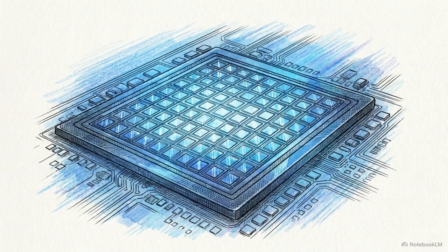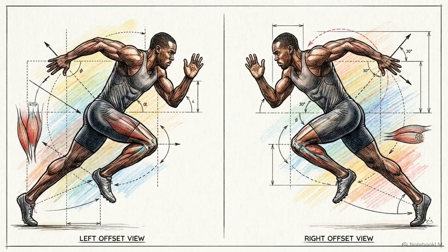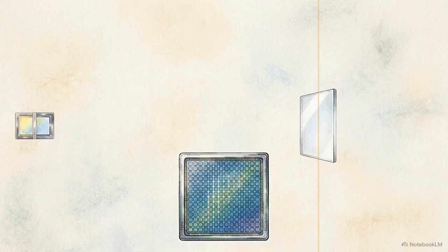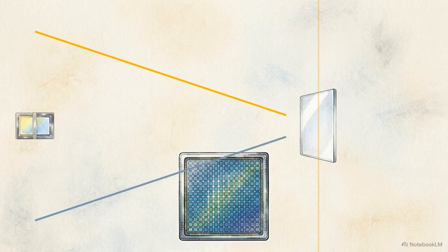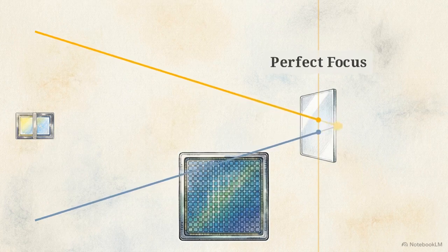Most modern cameras use phase detection autofocus, embedding thousands of specialized pixels directly into the sensor that act like 2 tiny eyes, looking out at the same subject from slightly different angles. In this sensor diagram, specialized pixels intercept and split incoming light into 2 separate streams. When in focus, these streams converge perfectly on the focal plane.